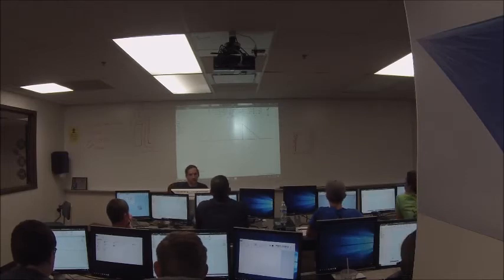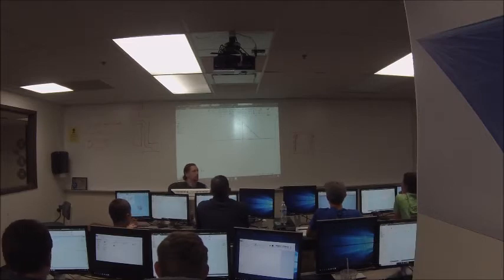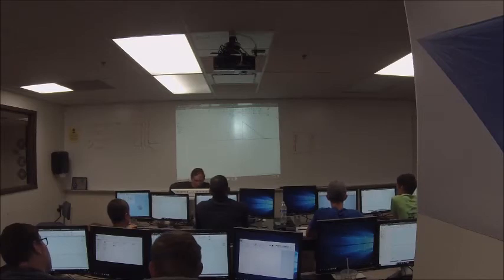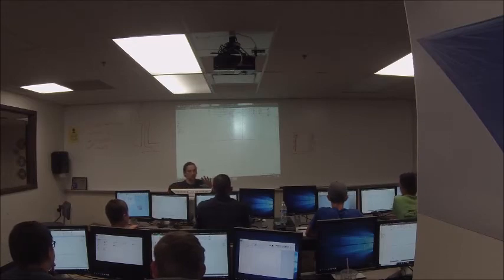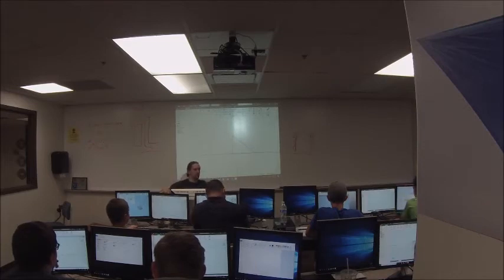So let's say I made this little triangle, right? I don't want this triangle to be a right triangle. I want it to be some other angle. And Inventor automatically placed a perpendicular constraint, so now I'm out of luck. So we want to delete the constraints. Deleting coincident constraints is slightly more complicated. What I'm about to show you applies for anything that's not a coincident constraint. We'll talk about how to delete coincident constraints here in a second.